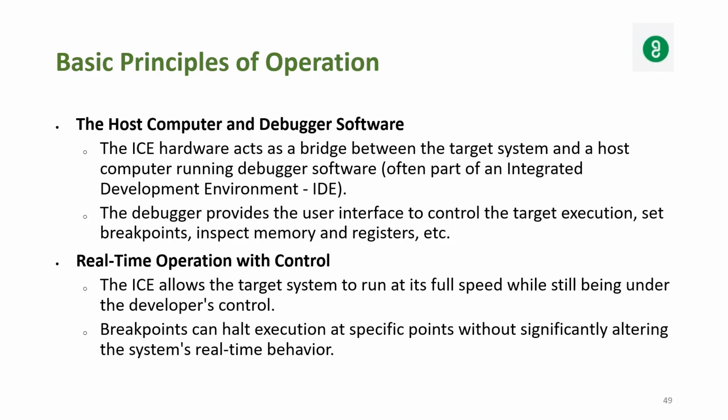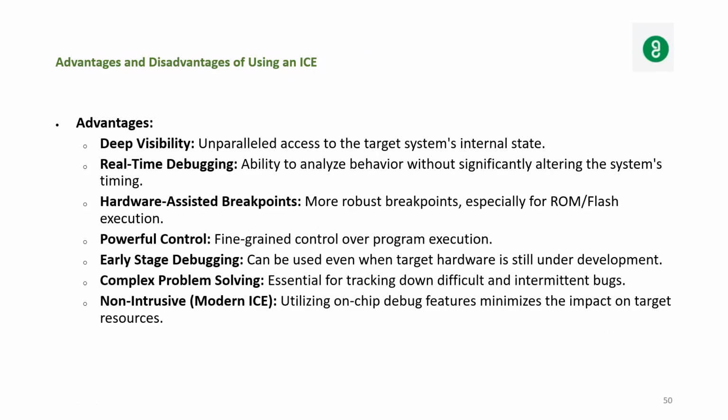The debugger provides a user interface to control the target execution, set breakpoints, and inspect memory and registers. Real-time operation with control: ICE allows the target system to run at its full speed while still remaining under the developer's control. So breakpoints can halt execution at specific points without significantly altering the system behavior.